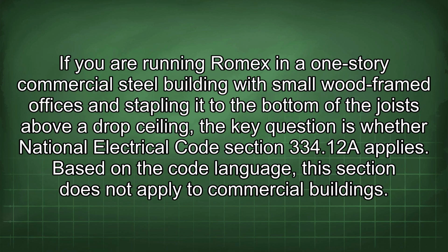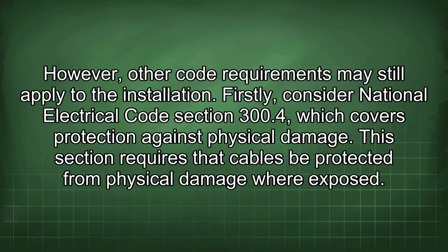If you are running Romex in a one-story commercial steel building with small wood-framed offices and stapling it to the bottom of the joist above a drop ceiling, the key question is whether National Electrical Code Section 334.12 applies. Based on the code language, this section does not apply to commercial buildings. However, other code requirements may still apply to the installation.